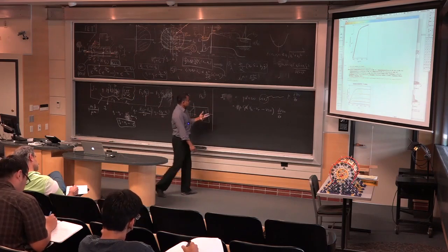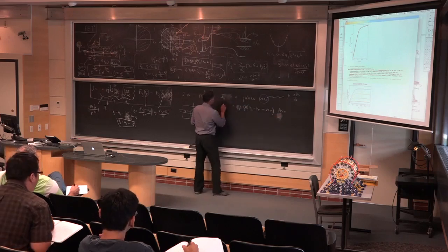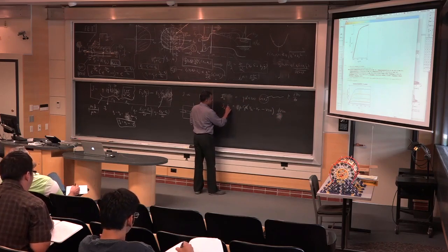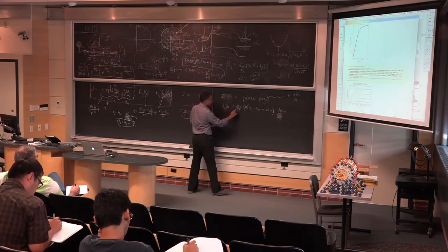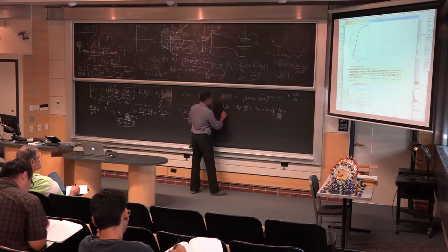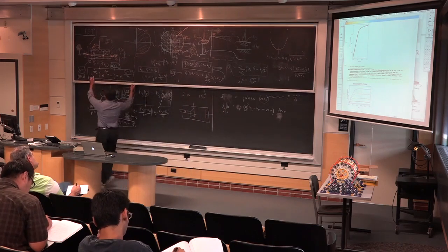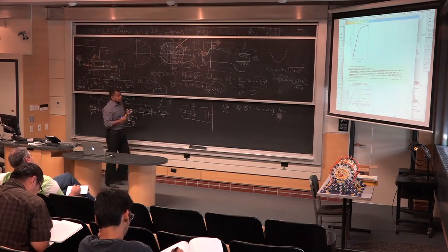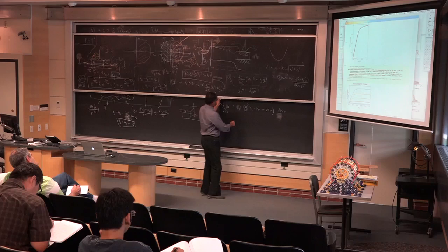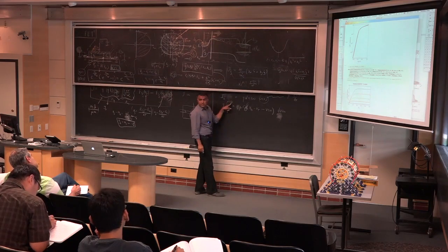And this is it. Once you look at this, what Shockley realized, since the current is continuous, let me bring that x over to the left. And you see now I've decoupled the two. And I'm going to just integrate both sides from x equal to 0, which is my source end, from here to there. So integrate it from source to drain, at x equal to 0 and x equal to L. That's the length of the channel, right?